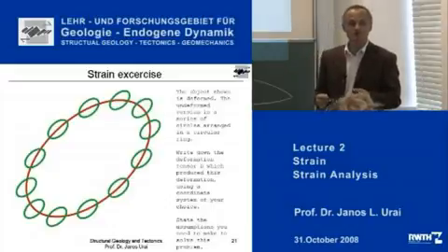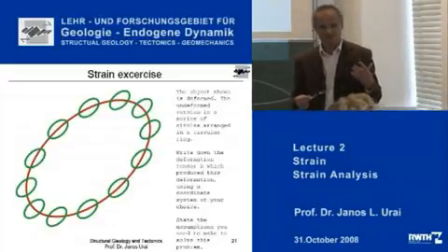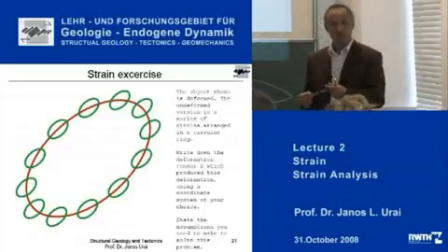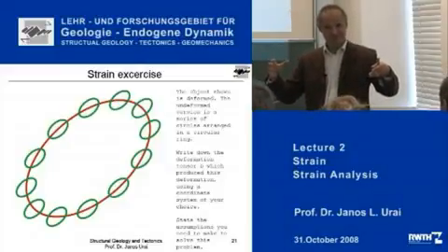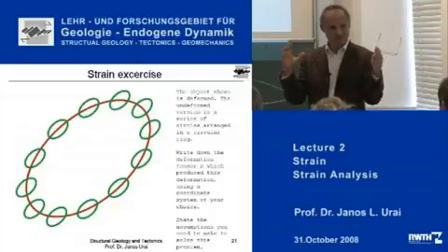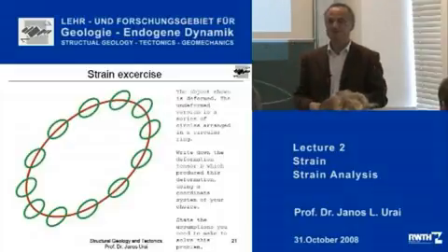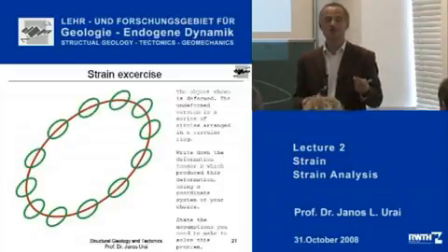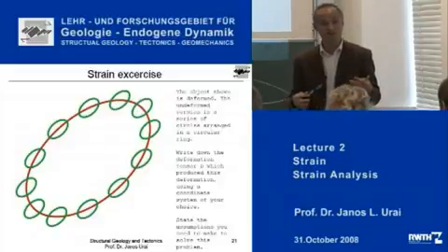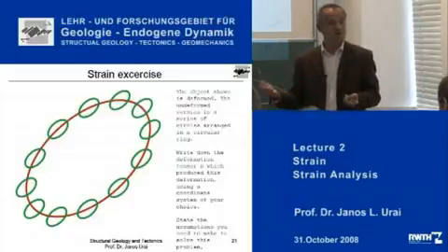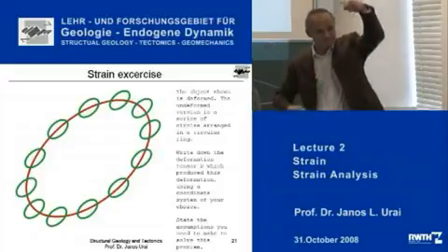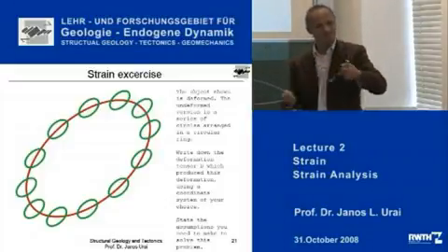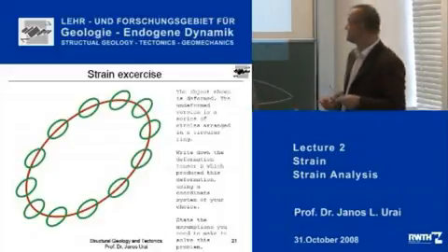And you can only calculate the D-tensor if you know the determinant of this matrix, which gives you what the area changes. Okay? So say you assume there has been no area change, then you can make the calculation. It was stretched exactly the same amount as it was shortened in the other direction, and then you can calculate the components.